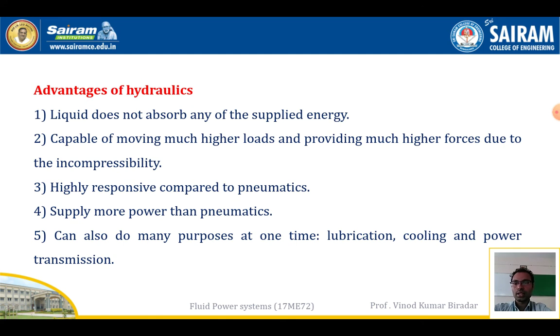So next one is, what are the advantages of a hydraulic system? Normally in hydraulic systems, liquid does not absorb any of the supplied energy, so this is one of the most important advantages. The second one is, it is capable of moving much higher loads as compared to the pneumatic system. Third advantage is it is highly responsive compared to the pneumatic system, so it will work very quickly, and it will not lose any oil content in the reservoir or tank. Fourth advantage is it supplies more power than pneumatic. As compared to the pneumatic system, it will supply more power to the given work.